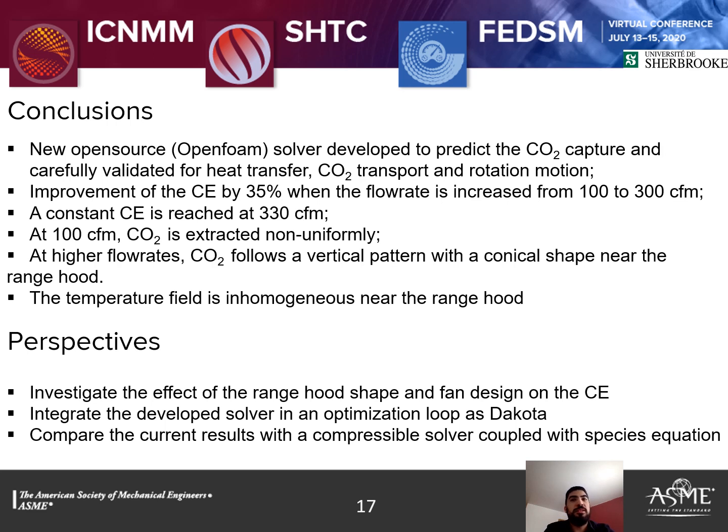The temperature field is inhomogeneous near the range hood. As perspectives, we want to investigate the effect of the range hood shape and fin design on the capture efficiency. We want to integrate the developed solver in an optimization loop such as Dakota, and then we want to compare the current results with a compressible solver coupled with the species equations.